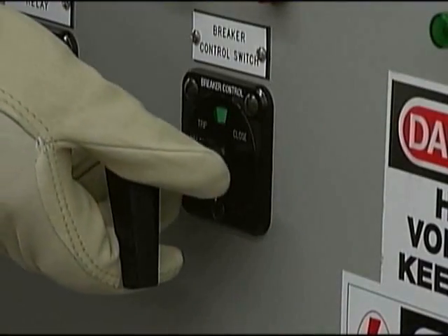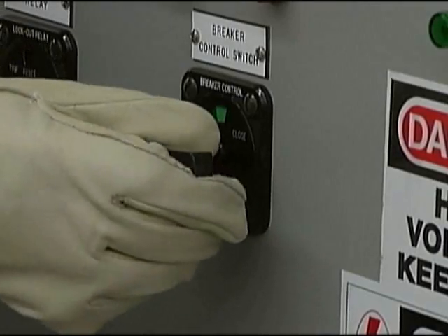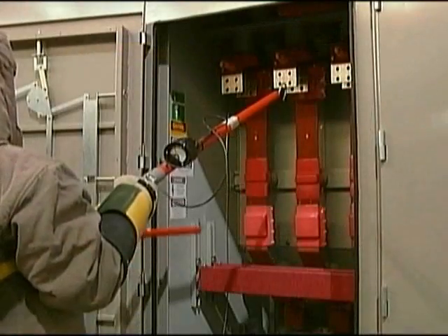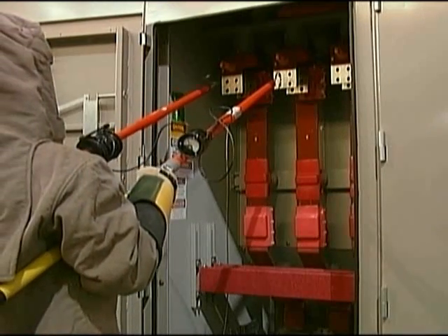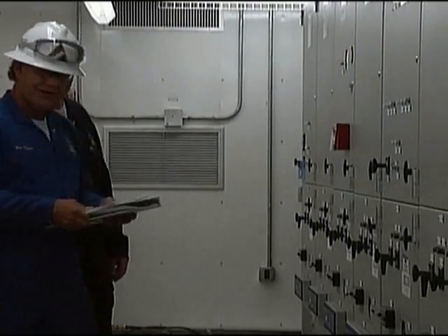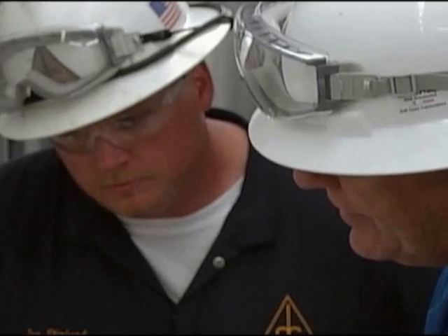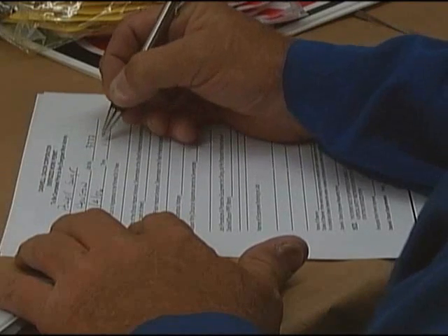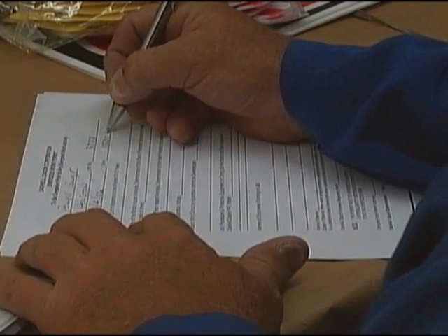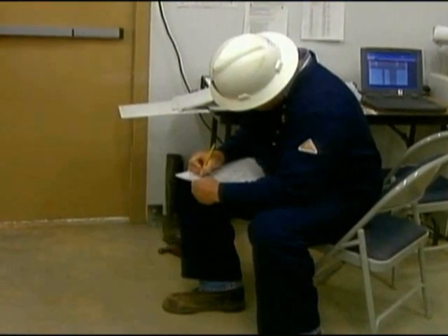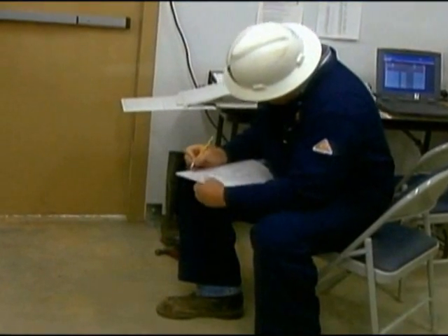All parts and lines 50 volts or greater to ground must be placed in an electrically safe condition by de-energizing it prior to a worker beginning work on the equipment. If it is not possible to de-energize the part or equipment, then prior to work, a written energized work permit and job safety task analysis is required. In addition, approach distances will be determined based on voltage prior to beginning any work.